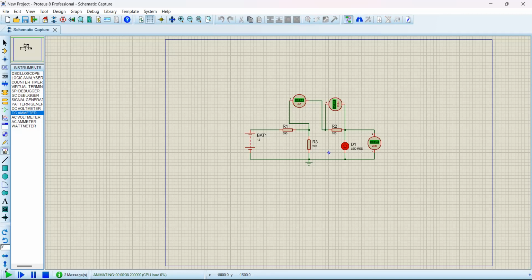When it comes to design, it will never tell you that the voltage is too much for the component that you're supplying. If you're supplying 500 volts on a resistor or an LED, it will be damaged, but you'll never see it in Proteus.